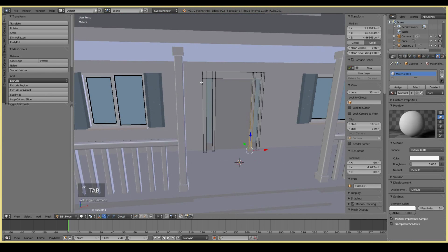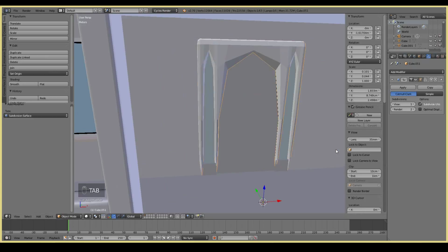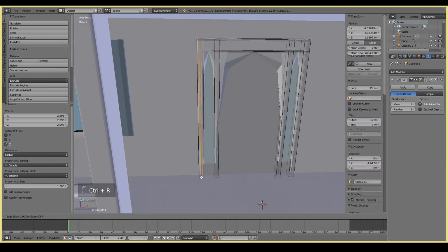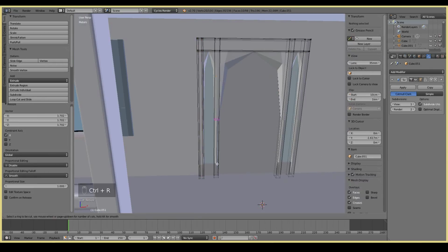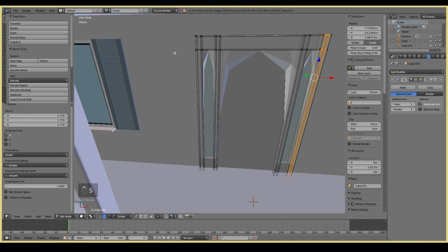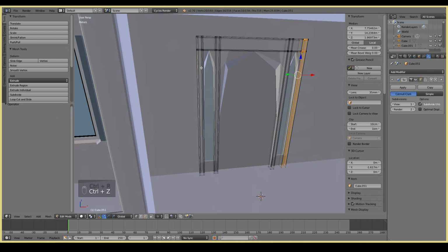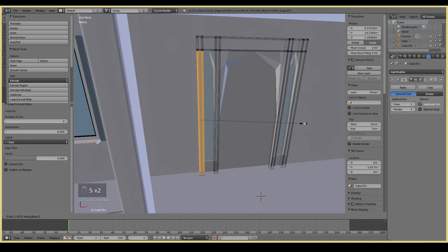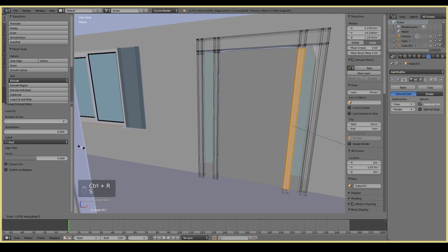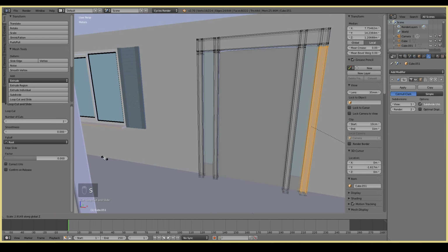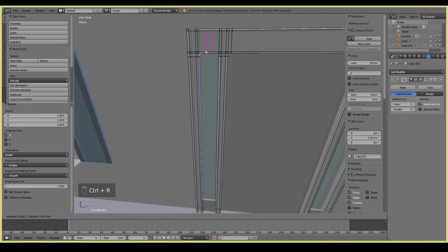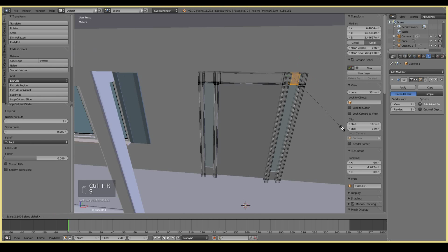So here I added a subsurface scattering to the support beam, and the main reason is that I wanted to get that smooth look. Doing a plain bevel would have been a little bit tedious in this case, because there's the edges here. I don't know, some of them just don't work properly, that I found. So I just go ahead and subsurface and then add loops around just to get rid of that sort of awkward look that you saw there. And the result is it's a very smooth looking model.